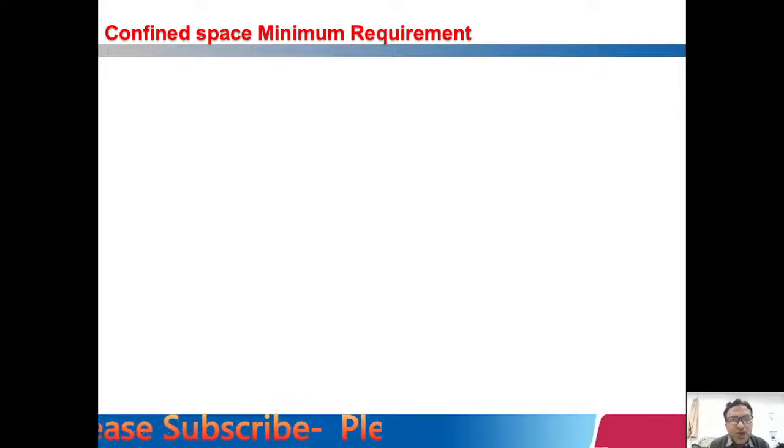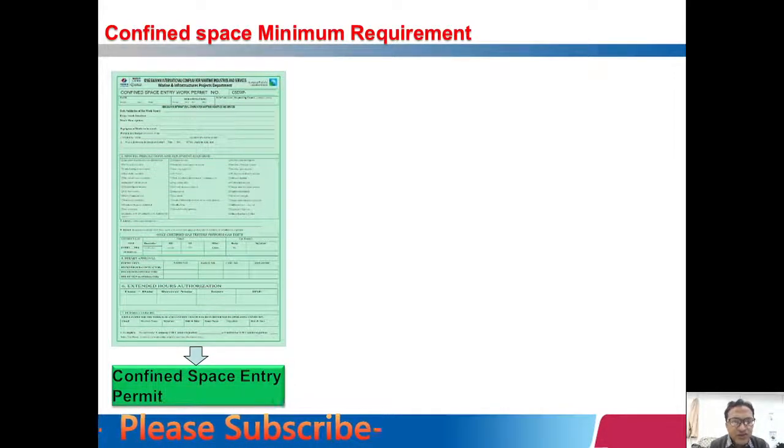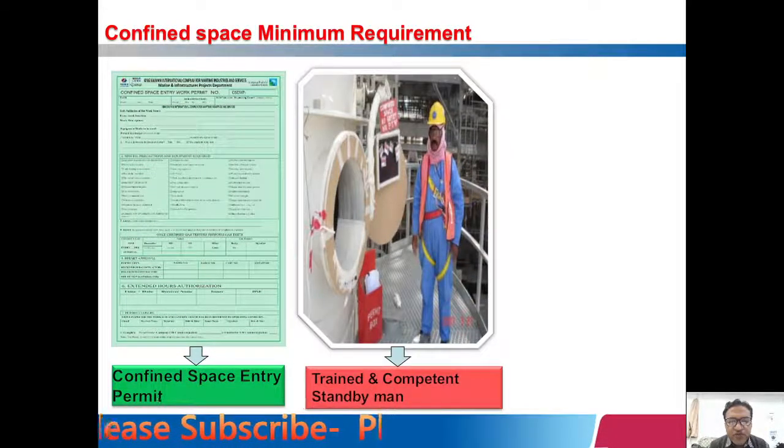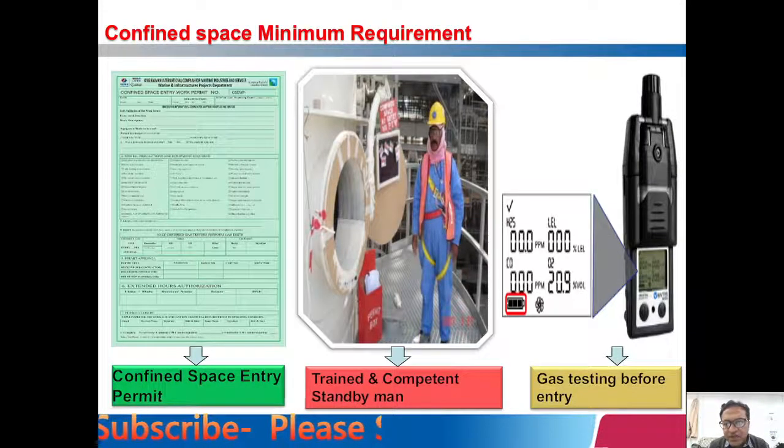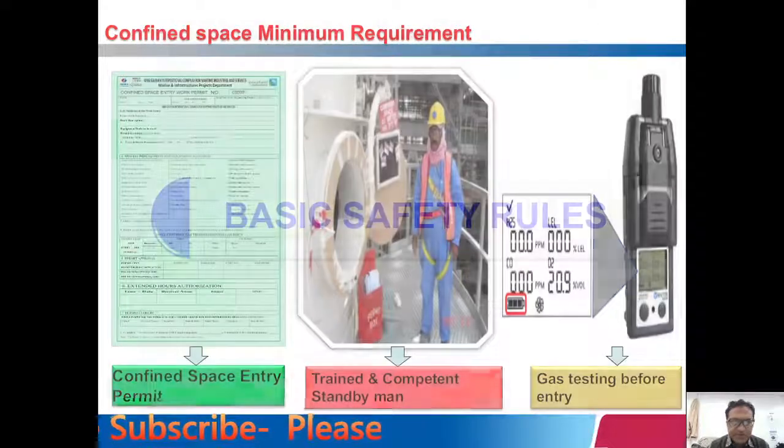Confined space minimum requirements, guys, keep in your mind that whenever you are performing work inside a confined space, there should be a confined space entry permit, there should be a trained and competent standby man outside of that space, and gas testing before entry. An authorized gas tester will come to site and check the gases. If the gases are under the limit, then he will permit you to perform the work inside the confined space.